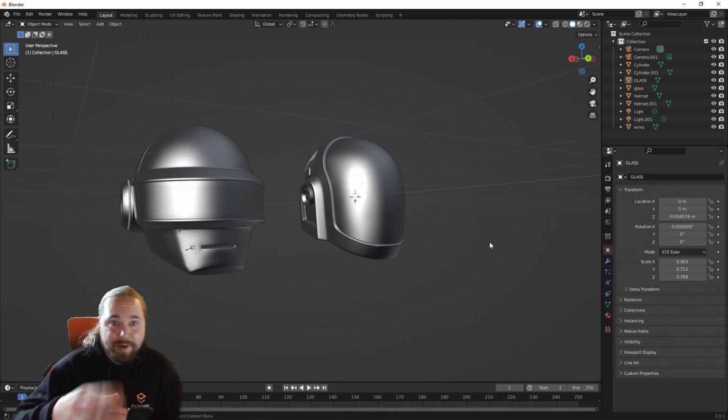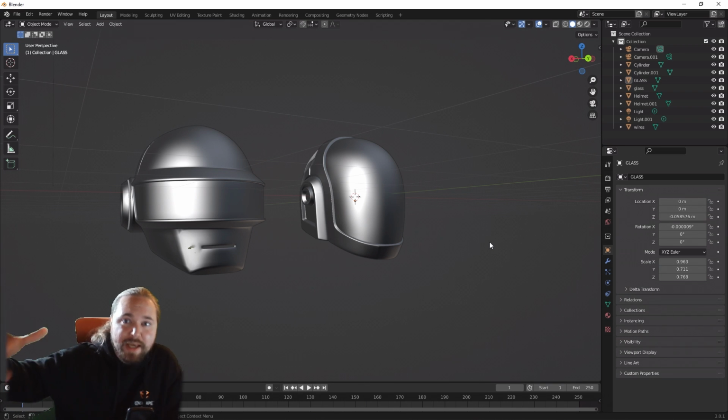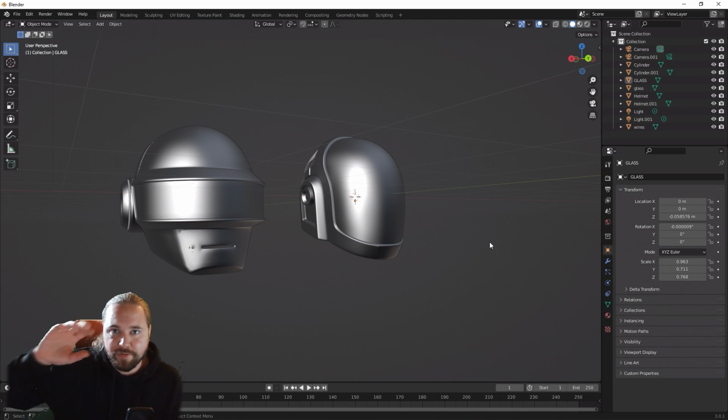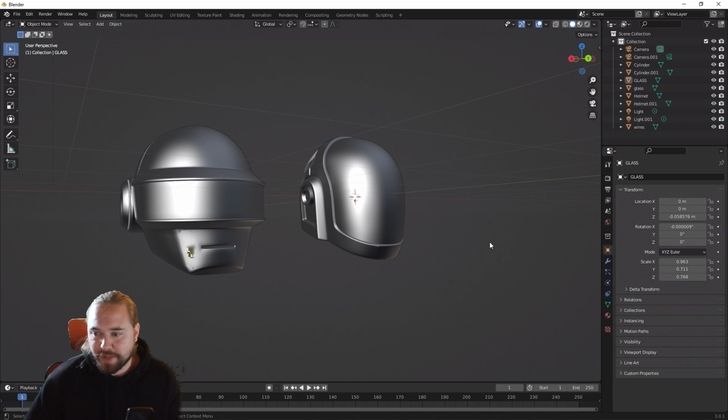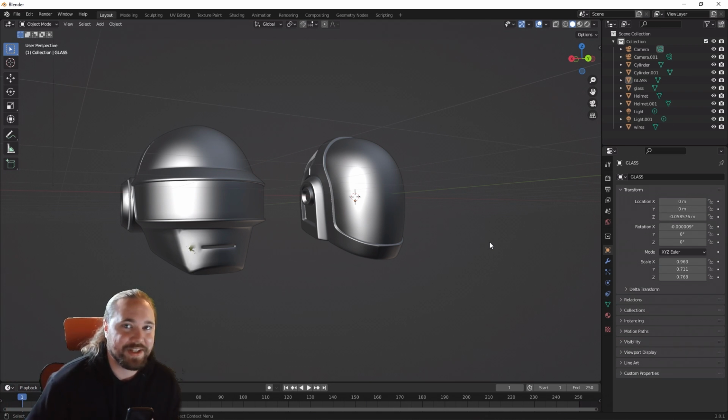It's going to be easy for me because my scene is empty anyways. But if it's a highlight model, something important for the scene, it's absolutely fine to bring in something larger than 20,000 polygons. However, also keep in mind, is it going to be big? Is it going to be visible? Or are you looking for a model that is going to be visible somewhere tiny in the distance? In that case, you don't need that amount of polygons.